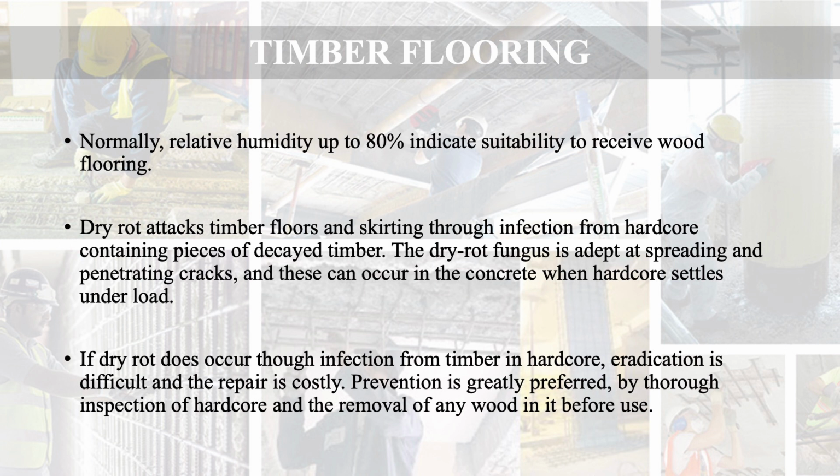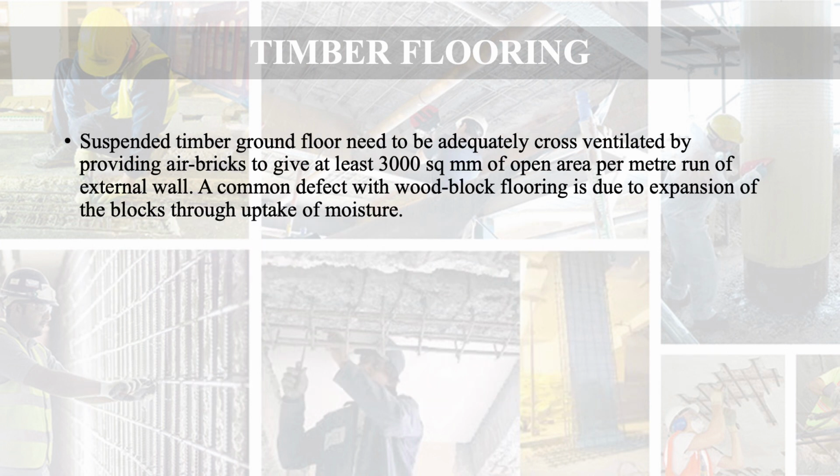further process. Suspended timber ground floors need to be adequately cross ventilated by providing air bricks to give at least 3000 square mm of open area per meter run of external wall. So if you do that, you can ensure proper cross ventilation.